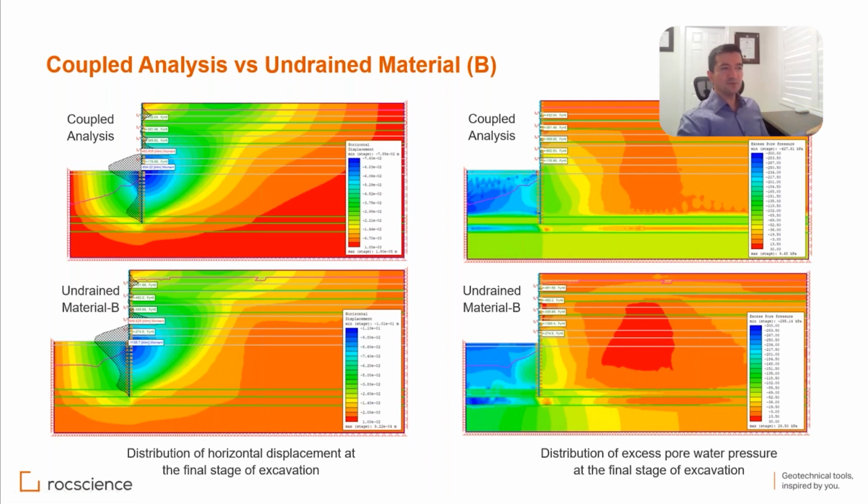What I would like to mention as a side note is that you can see the coupled analysis in this area and also undrained B in this area. This seems to have a little bit of an issue with numerical stability because that's the coupled formulation. It's harder to solve that system of equations, and also we are doing that correction for the unsaturated case.